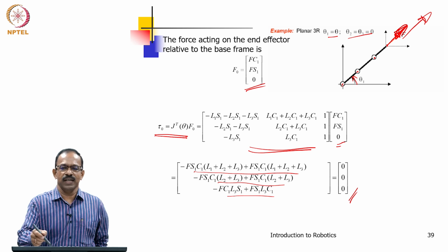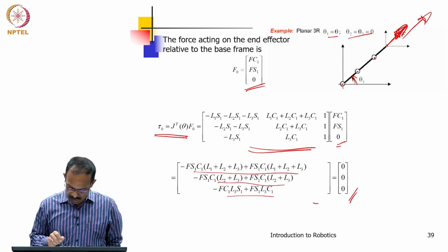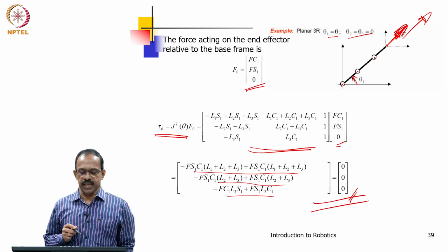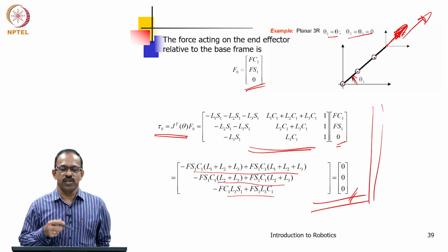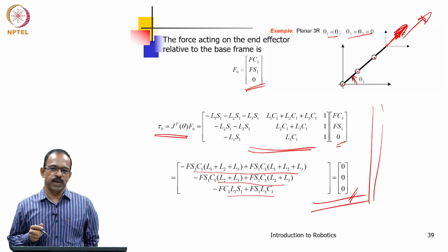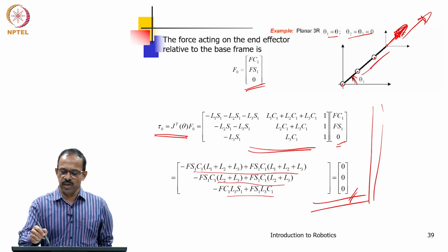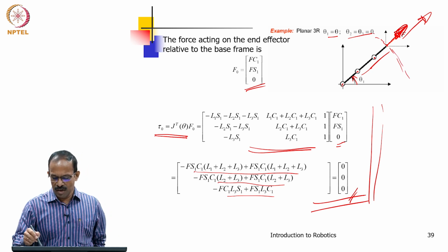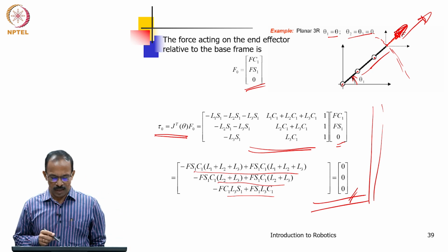That force is not really reflected onto the joints, and this situation is known as lockup or force singularity. It is another situation encountered when the manipulator is in a singular configuration, and it actually comes from the boundary singularity of this particular manipulator.